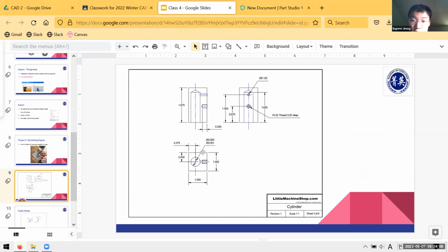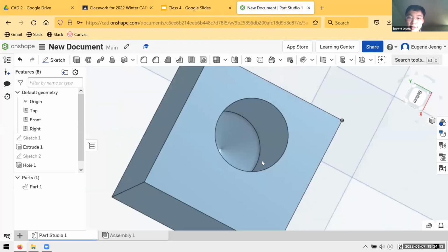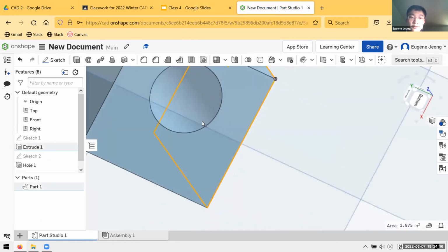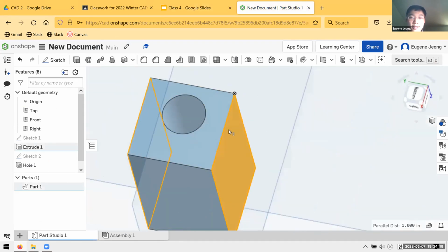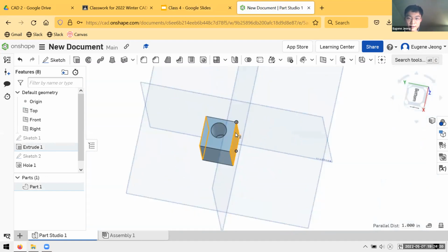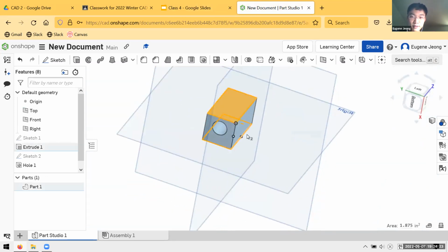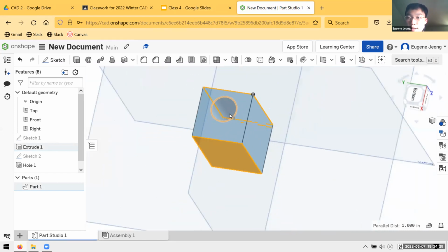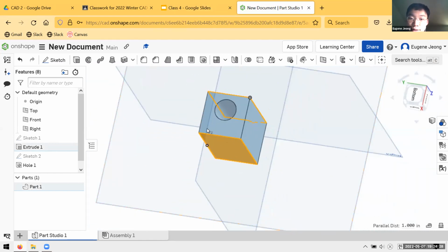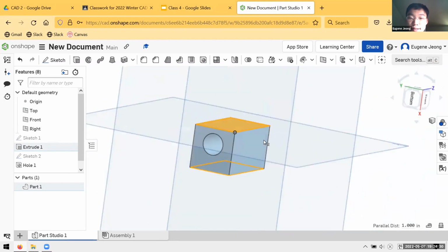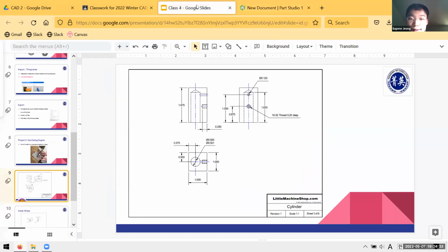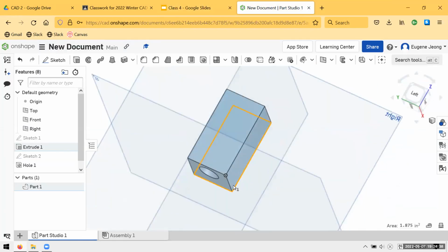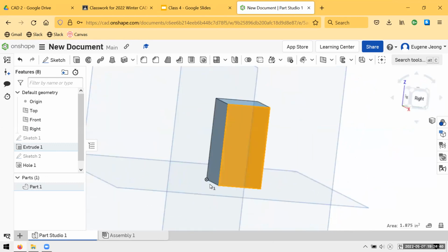The important thing to notice here is that the holes come in from the side where the hole is far away from, right? Looking at this, it's symmetric left and right with respect to the line of symmetry here, but it's not symmetric with respect to these two. So we're going to be careful to pick this face and not this face, since that's how it is in the drawing. We're going to pick the one that's side is farthest away from the circle? Yes, indeed.